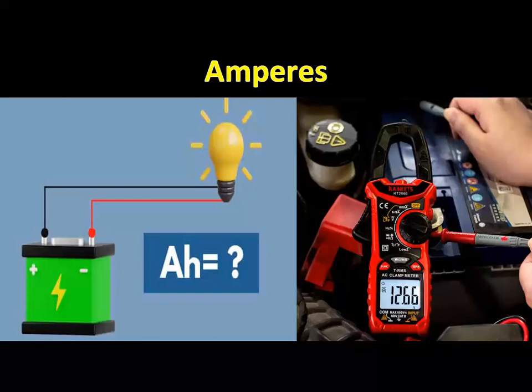Excessive amounts of electrons, or amperes, flowing through a conductor will cause heat buildup. This in turn will raise the resistance in the conductor and drop the voltage in the conductor. This action will force the circuit to increase the electrons flowing to maintain the circuit, thereby increasing the heat. This cycle can happen very quickly, with devastating results to wiring and electrical components if the right size and type of conductor is not used.